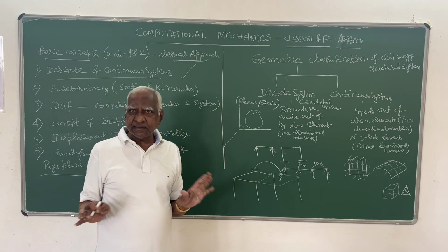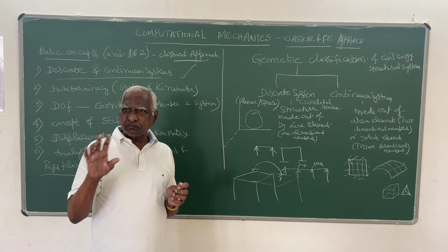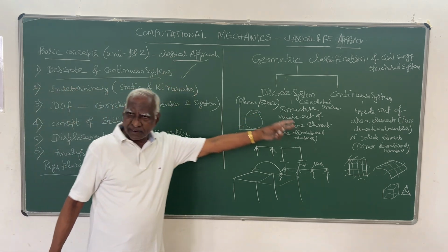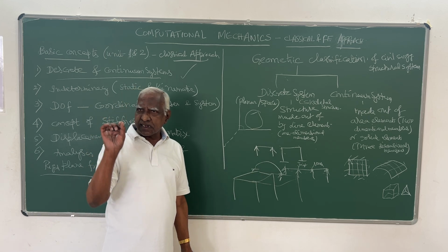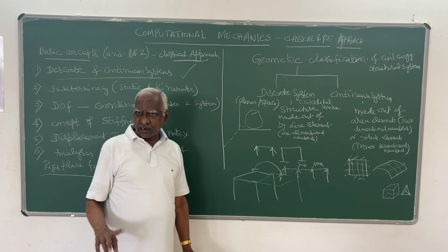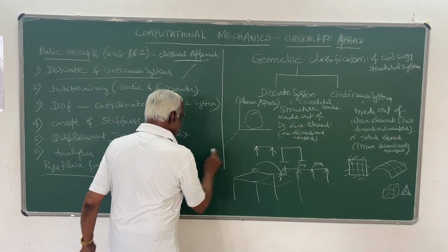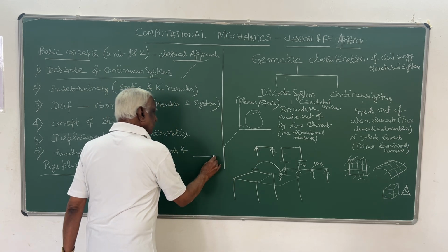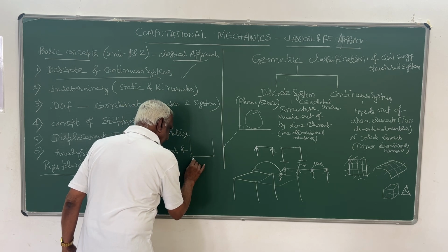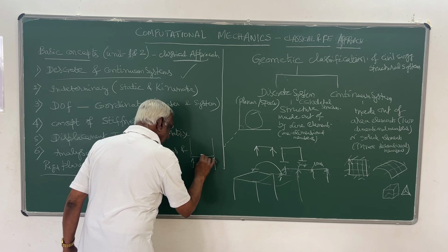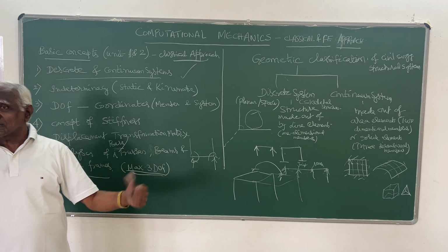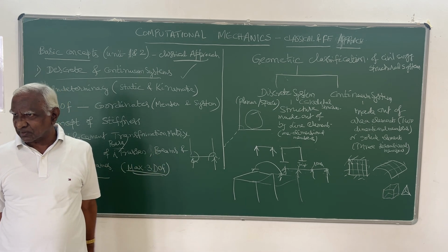So that means, in a nutshell, all the unknowns that we have to determine during our analysis of all these structures are considered only at the joints. Internal stresses are this: if you take a beam member subjected to loads, the internal stresses developed in the beam, that is the shear as well as the moment, have to be considered only at the joints or ends of the member.